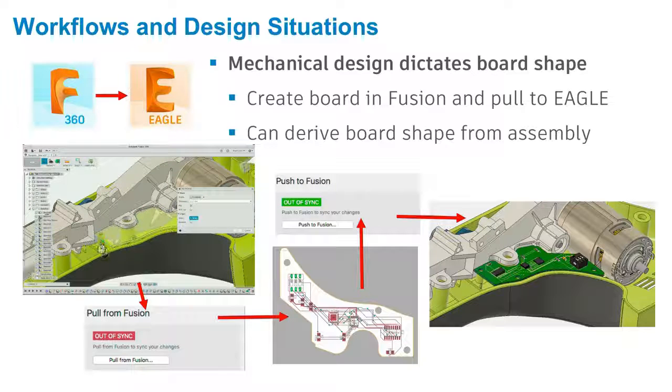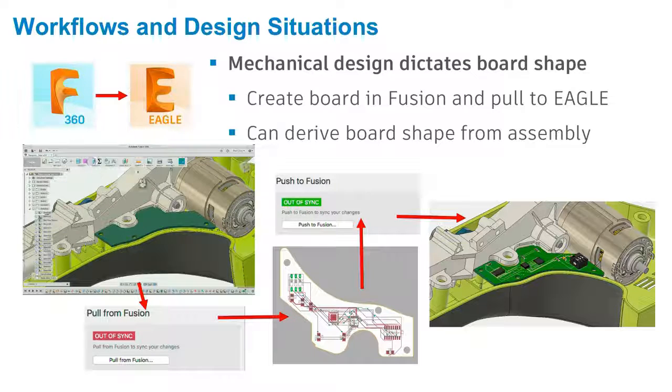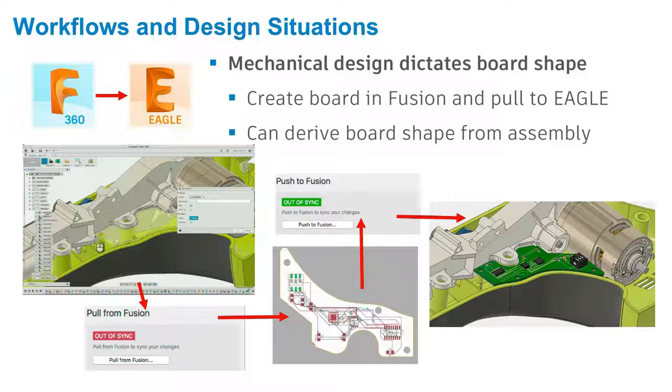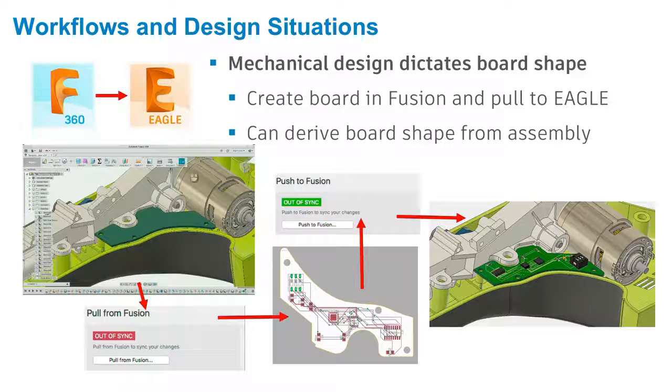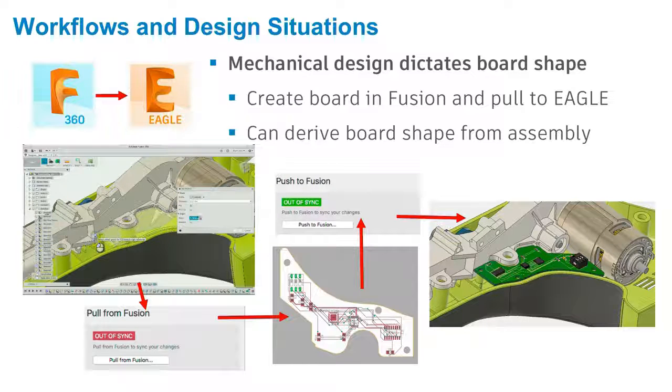Now with this new system, he's able to project that complex outline, and I'm able just to pull it into Eagle and actually populate it. And then as soon as I populate it, he gets the information and is able to now see if the board actually will work for him and see if the heights will work for him as well. Yep, and if we needed to move anything around on the board after we see the PCB components, we could easily do that and then pull back to Eagle. Now, this is going to be a very common workflow because usually the board outline will lead this dance. Usually the mechanical engineer, the board outline, he's going to actually be working with some sort of enclosure. So this is a very, very common workflow.